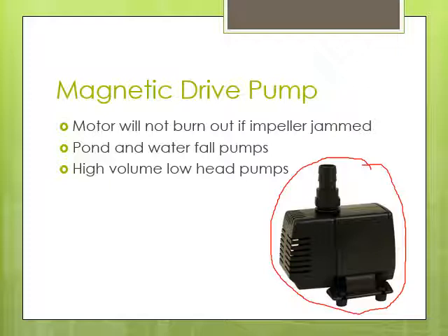They are really good for low pressure, fairly high volume applications, and the fact that they're waterproof and there's no bearings, the entire thing is pretty easy to maintain. In fact, you can remove the cartridge and buy another one. They have an impeller on it. I'm terrible at drawing. You can slide it out and put a new one in, and your pump is back to new again. So they're pretty easy to maintain.